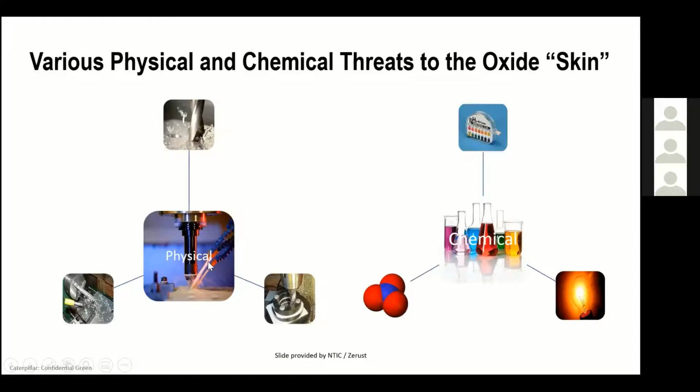But now that you're introducing moisture or water, you have to make sure that water has rust preventatives in it, and that it's good quality water, so that you don't accelerate the corrosion during the manufacturing process. Because what we've learned is that with oxygen, moisture, and metals, you're going to have corrosion. So we purchase different chemicals for that, and we want to make sure we manage them.